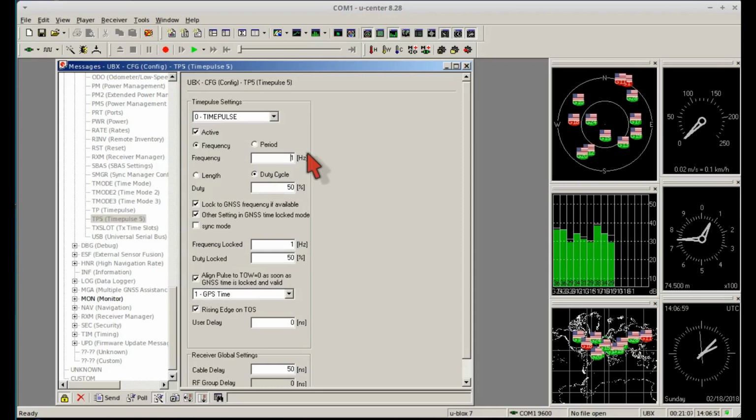If you have confidence that the local oscillator in the GPS isn't drifting too far off during periods of no reception, you can use the upper field and still generate frequencies. Or you can just set it to 4 Hz and leave it at that, so when you suddenly notice the PPS LED blinking frantically, you know you've just lost satellite reception.